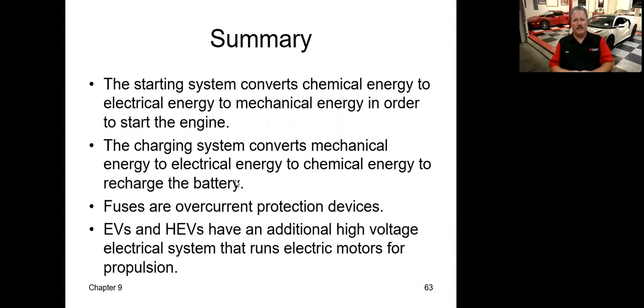So there you go. The starting system converts chemical energy into electrical energy into mechanical energy to start the engine. The charging system converts mechanical energy to electrical energy and keeps the battery charged up. Fuses are basically overcurrent protection devices. In other words, fuses protect circuits down the line from burning up. It's best to change a 50-cent fuse versus a $500 stereo. And electric vehicles have an additional high voltage electrical system that runs electrical motors for propulsion.